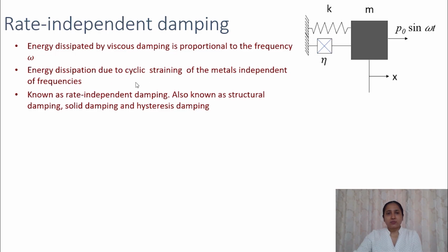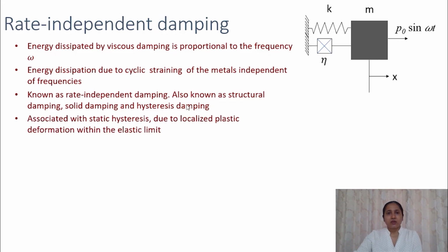This damping is also known as structural damping, solid damping, and hysteresis damping. It is due to localized plastic deformation in the material within the elastic limit. So this is a static hysteresis. At very localized positions, plastic deformation is happening, and because of that some energy is getting dissipated, and that energy dissipation is independent of the forcing frequency.